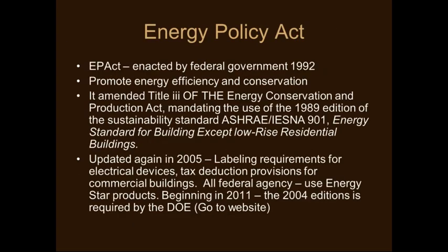The Energy Policy Act, which is the EPAct, was enacted by the federal government in 1992. That's where we start to promote energy efficiency and conservation. It amended Title III of the Energy Conservation and Production Act, and it mandated the use of the 1989 edition of the sustainability standards, ASHRAE/IESNA 90.1.